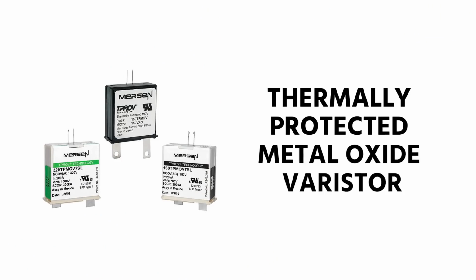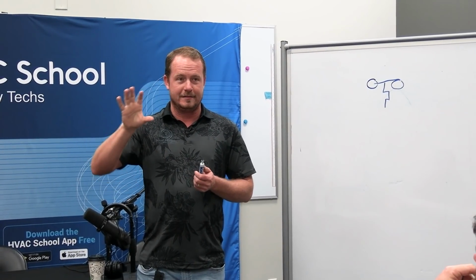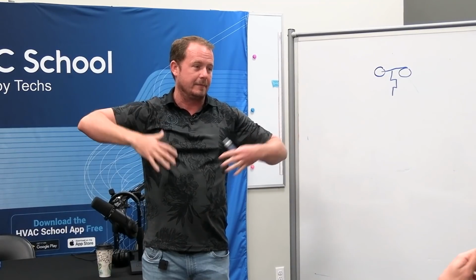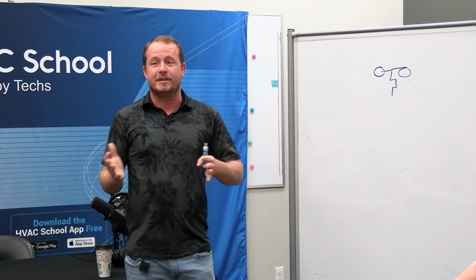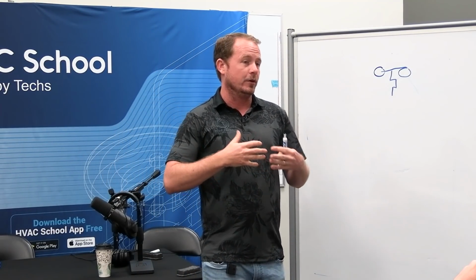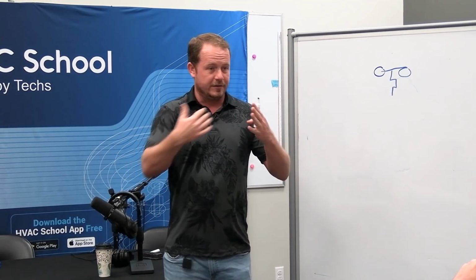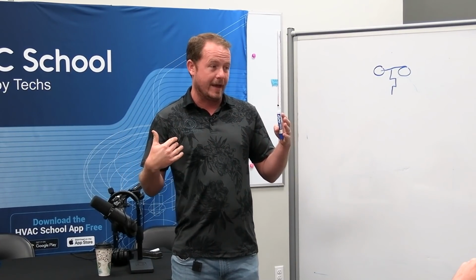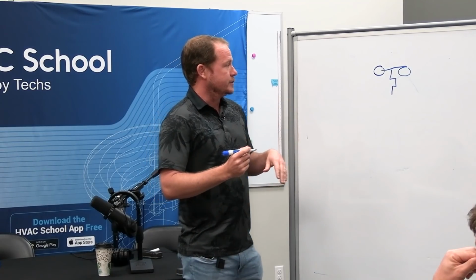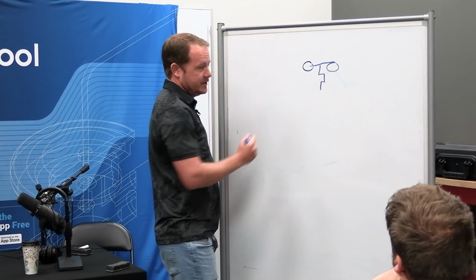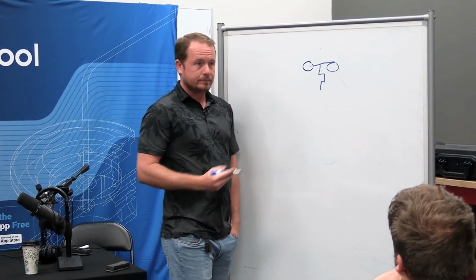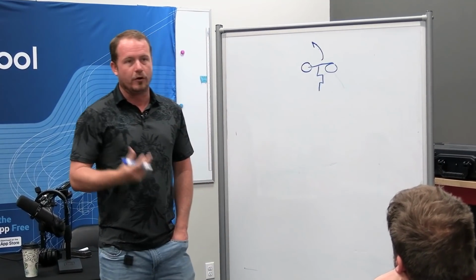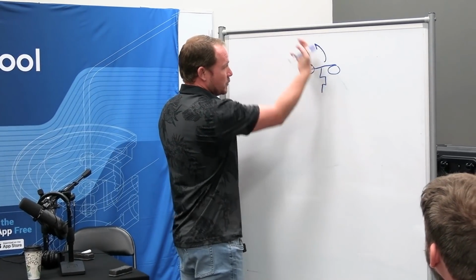And the reason that it does that, if you've ever seen some old photos of some of the older types of surge protectors, where there's like a big flame on the side of the house where it melted the siding, that's what used to happen a lot with surge protectors. They would go into thermal runaway. It would start shunting current to ground, which is how they work when there's a lightning strike or something, but then they would get stuck doing that until the whole thing just melted down. A modern surge protector has a thermal limit in it, and this is how a thermal limit is drawn. It's normally closed, but if it gets too hot, this is the symbol for a thermal switch. If it gets too hot, then it forces the switch open.